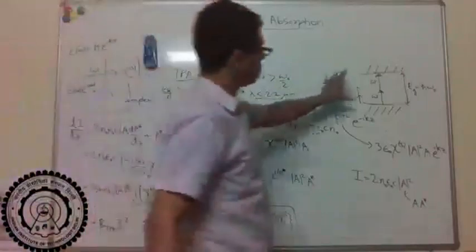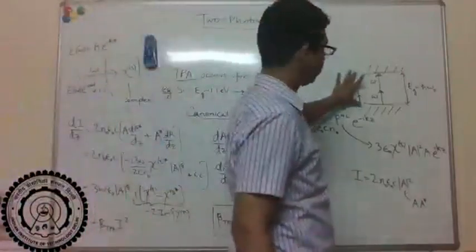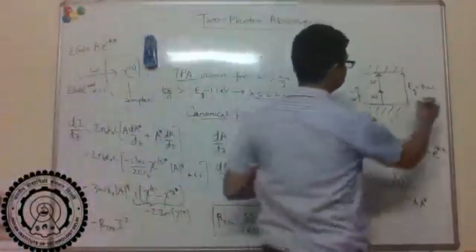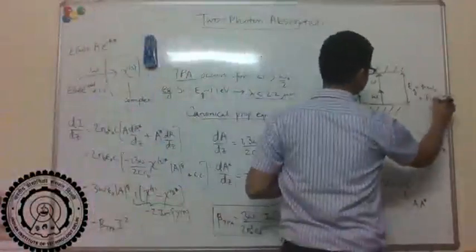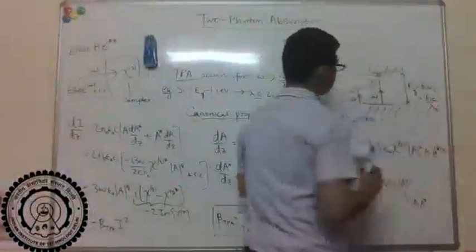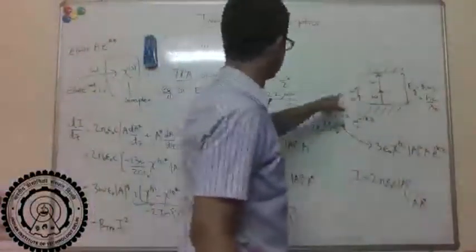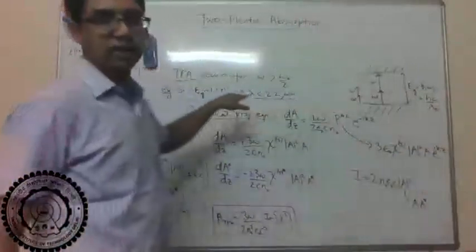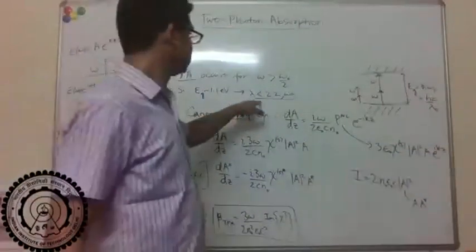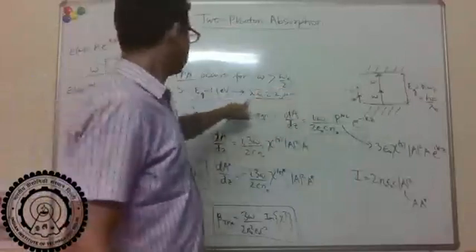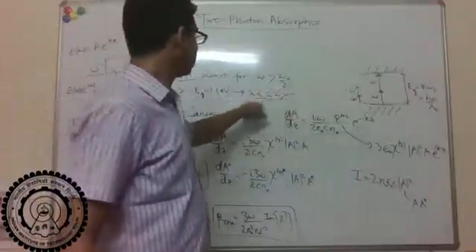Right, basically a single photon resonance wavelength. So if I write this as hc over lambda naught, that lambda naught corresponds to 1.1 micron, and so you need at least twice the wavelength or half the frequency to avoid TPA. Right? So if your wavelength is less than 2.2 micron, then you get TPA.